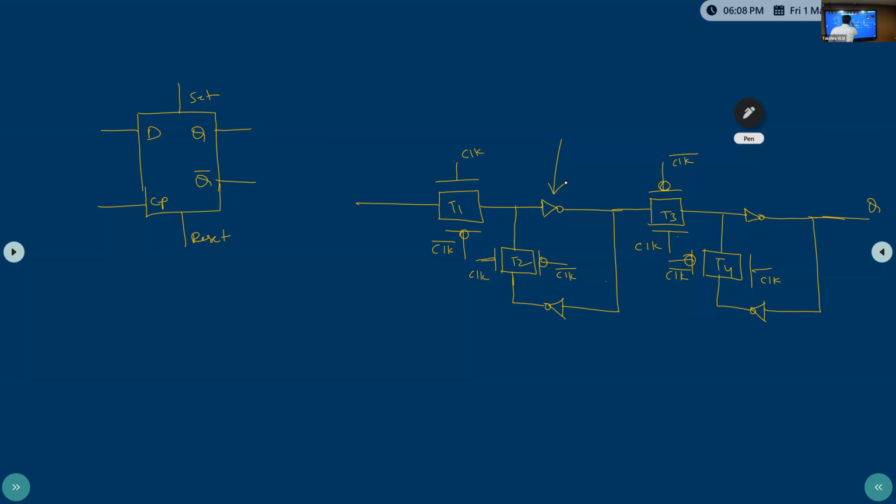So what is the use of this transmission gate? A transmission gate uses both NMOS and PMOS together. One PMOS and one NMOS will be there. If the signal is 0, NMOS will be turned on and the output signal will be a stronger 0. If the signal is 1, PMOS will be turned on and the output will be a stronger 1. Whatever signal comes at the D pin, the strongest signal needs to be passed to inverter 1 and inverter 2, inverter 3 and inverter 4.